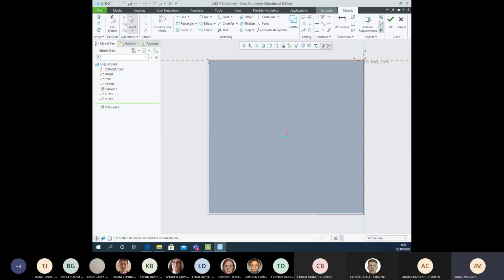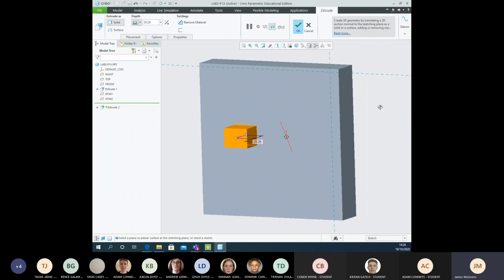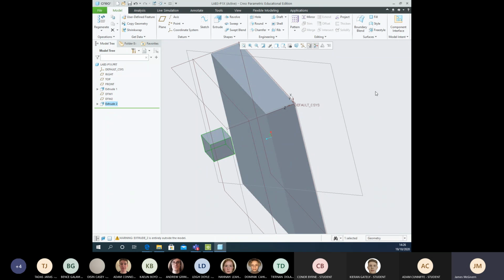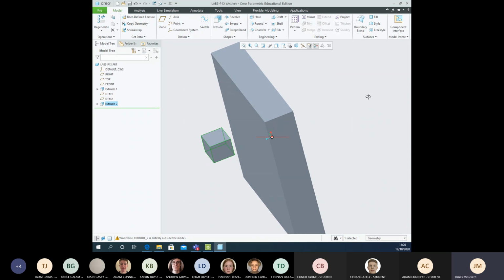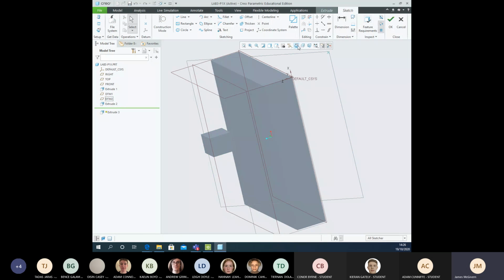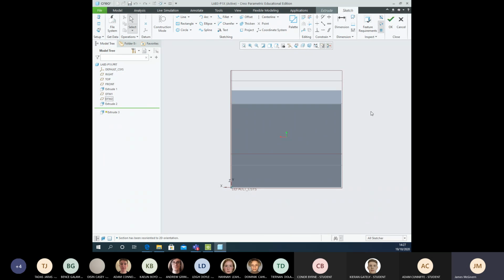And now I can do a shape here or whatever I want to do. So I'll put in a center rectangle just for demonstration purposes. I won't do anything with the size. I'll leave it as it is. And I'll say OK. And you can see I have a shape, an extrusion on that plane. That's OK, accept that. And now I'll do an extrusion on the other plane I made, the angle plane, which is DTM2. So I select DTM2 and select extrude and select 2D view.